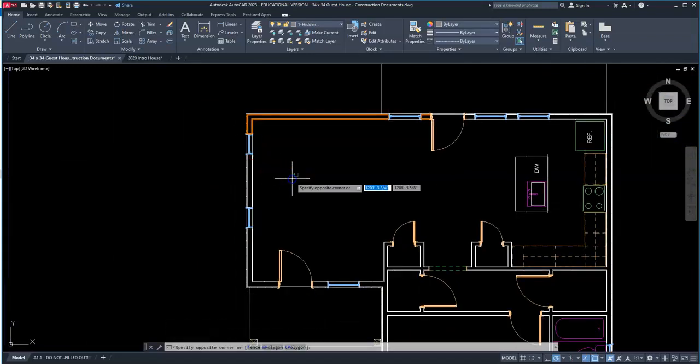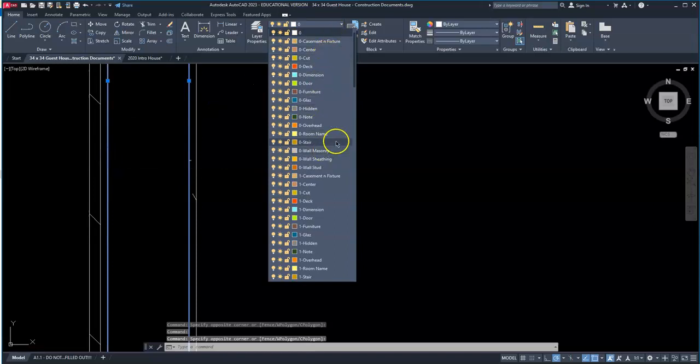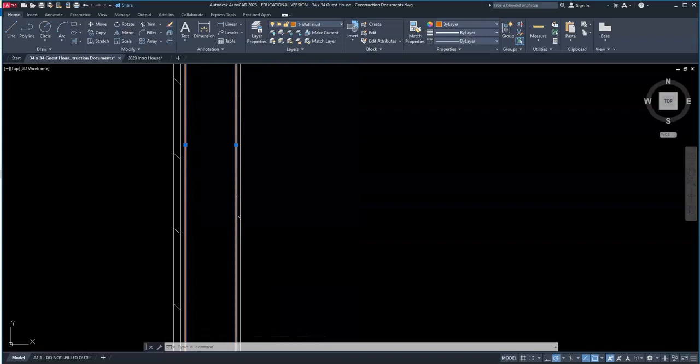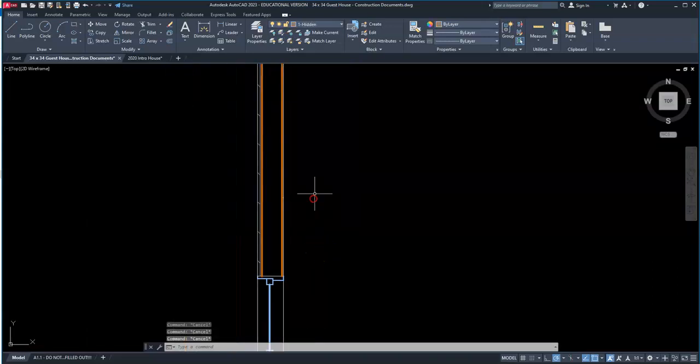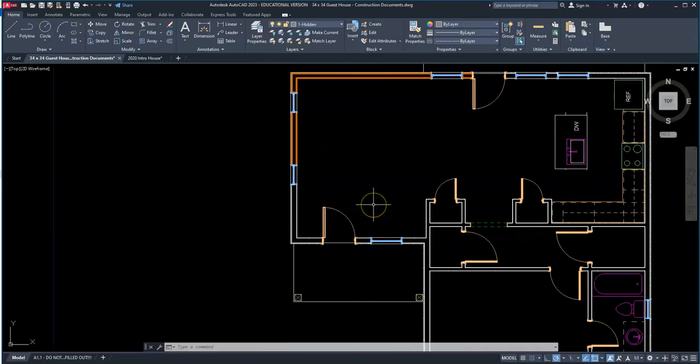So at this moment, we are going to go through and select every stud wall or stud line that you see, and we will select 1 wall stud. So this is a little bit of a tedious process, but the end result's much better than what Revit exported and gave us. I've done floor plans in the past where we stuck with the Revit layers, and when you print it, it just doesn't look as clean as it would if we did this manual work ourselves.